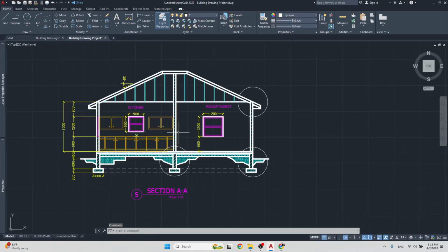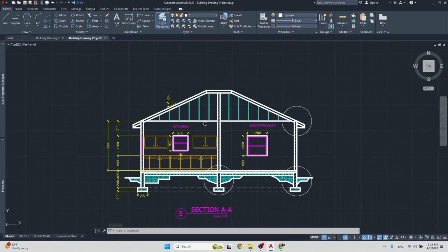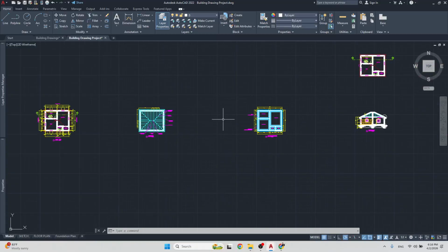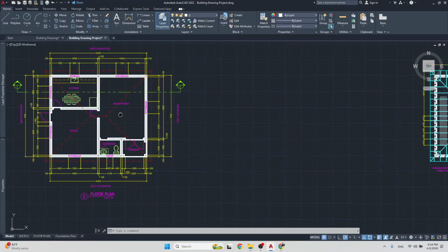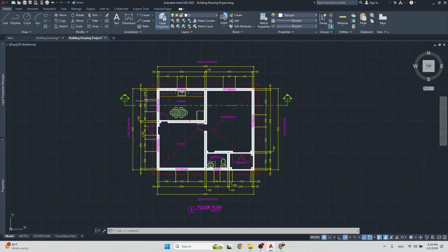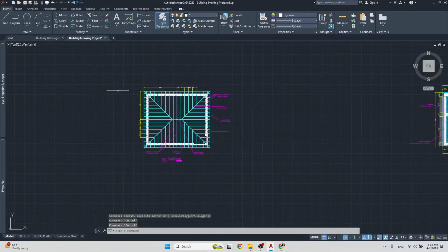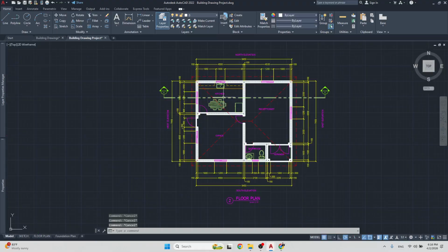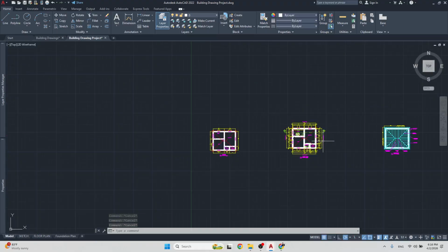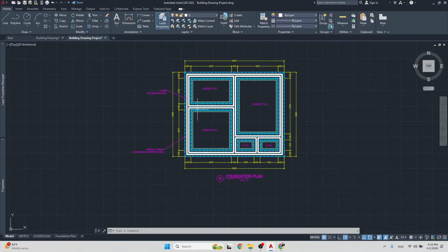Well, if you don't know, a section drawing is basically a cut through of the house from the roof all the way down to the foundation. So this is the house, the floor plan of the house. We have this cutting plane line that is cutting through the house, and this cut is cutting through, you can see the roof, the members of the roof. It's going to cut through the roof right here, and then it's going to come all the way down to the walls of the house, and then it's going to get its way down to the foundation, through the floor, then the foundation wall and the footing and the dirt and everything. It's going to cut all the way through.